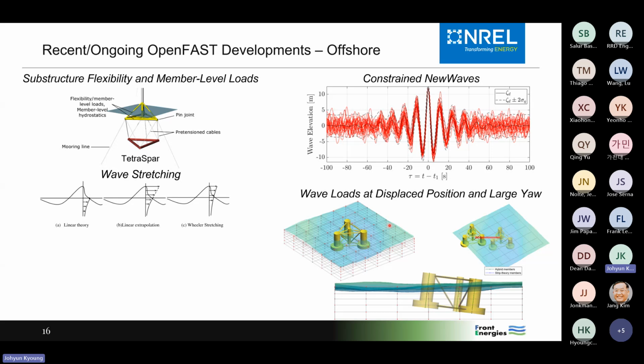So if I surge 50 meters that way, I have the solution for if it's over there. And so then at any point in time, we just interpolate within that big domain. So we get the right phasing of the wave. Really important if you have large displacement. Usually you do have large horizontal displacement, right? But that's how it's done in Orcaflex actually. So you have this low frequency and wave frequency, right. But I do not understand. This is all included in your global performance analysis. Yes. Everything is in.